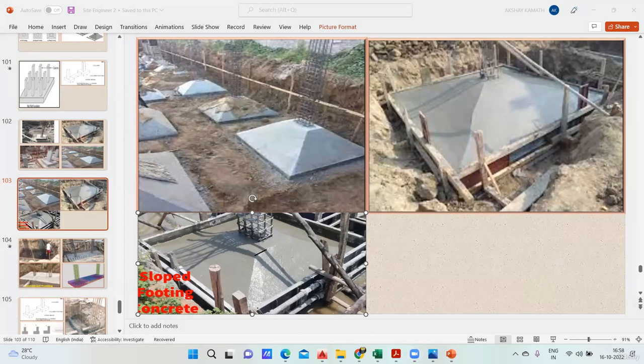After that, I had this column dimension of 500, and then I had this 75. This much is understood; length side I did. In the same way, breadth side also I want to do. Again here this will be 75, breadth side column dimension was 400 mm, and then again 75. You're getting my point. Now if I multiply this portion into this portion, am I not going to get the complete area of the top side? Obviously I'm going to get the same thing.